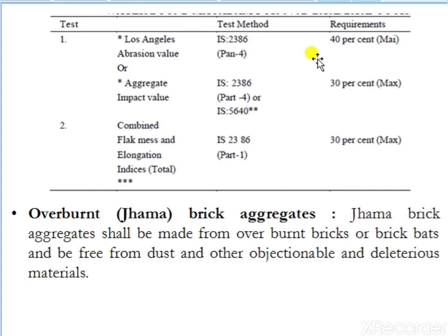Or else, if the coarse aggregate used in the construction is elongated, then it will have sharp edges, and when these sharp edges are subjected to a vehicular load, they will undergo breaking. So when the material breaks, it is said that the material has failed under loading condition.